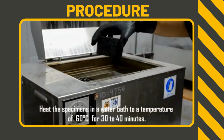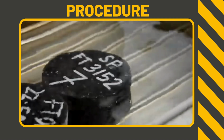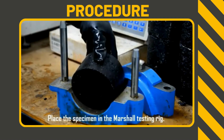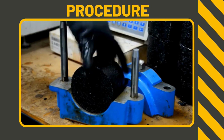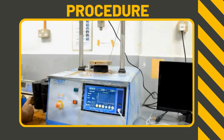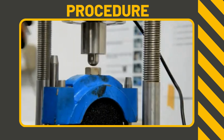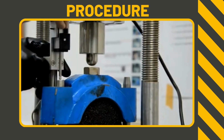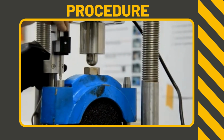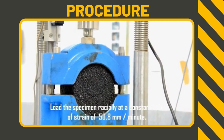Heat the specimens in a water bath, to a temperature of 60 degrees Celsius, for 30 to 40 minutes. Place the specimen in the Marshall testing rig. Load the specimen radially at a constant rate of strain of 50.8 millimeters per minute.